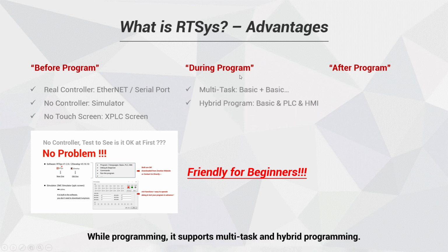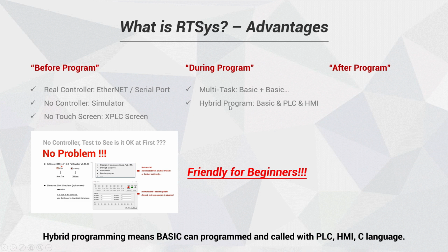While programming, it supports multitask and hybrid programming. Multitask means several basic files run at the same time. Generally, most controllers support max 22 tasks synchronously. For specific information, please read the user manual. Hybrid programming means BASIC can be programmed and called with PLC, HMI, C language.